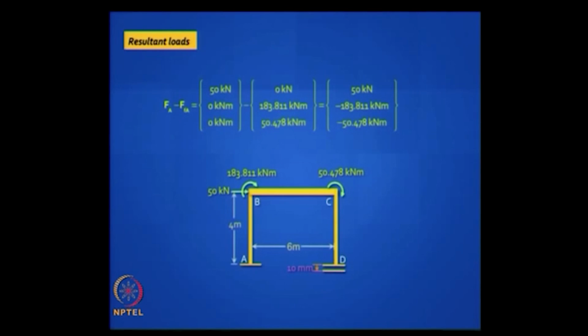Is it clear? So I don't even need to do that exercise. And so this is identical to slope deflection method, but you made an assumption. Assumption is actual deformations are negligible. How true that is for this problem we will know shortly. So you have got these moments. So your problem is now reduced to this problem, 3 loads, no vertical loads.